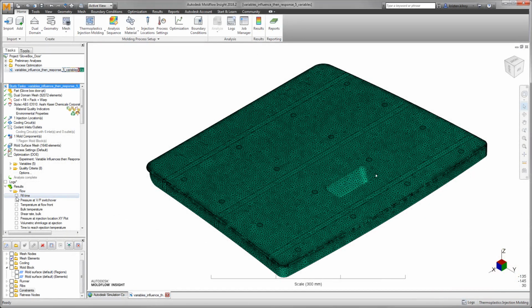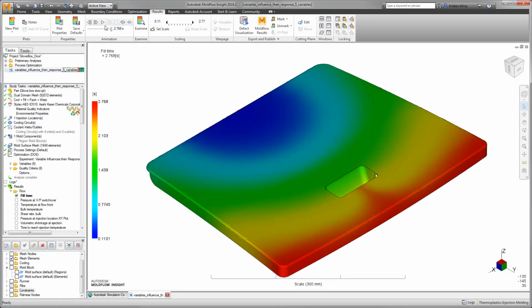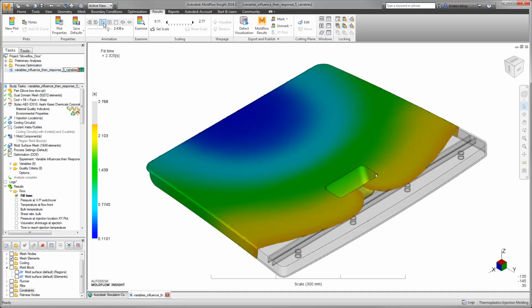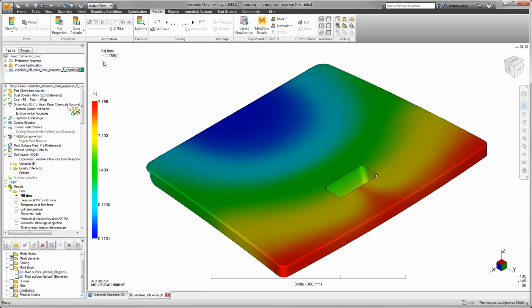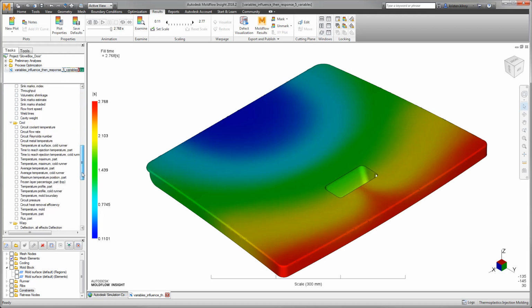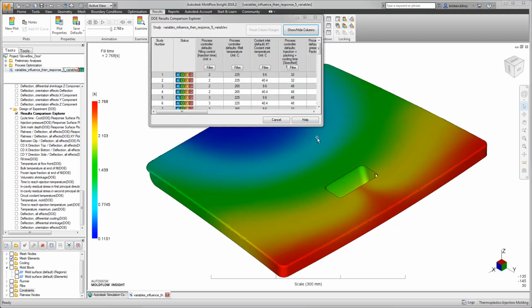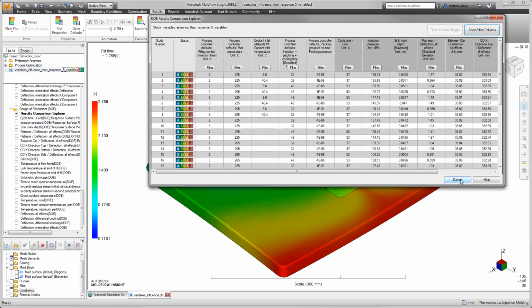This is where Autodesk Moldflow Insight can help. By digitally simulating the injection molding process, steps can be taken to optimize the part geometry, tool geometry, and process settings to help improve the manufactured part's quality. Part quality includes items like specified dimensions and visual aesthetics, so when molding a part, it is important to understand the effects process changes have towards these.